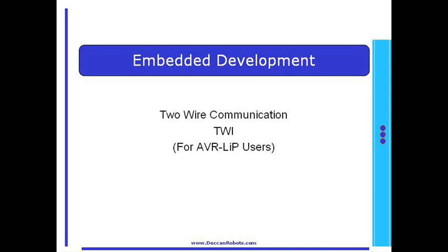The 8255 IC was used to convert one 8-bit port to multiple 8-bit ports. These multiple expanded ports were used to connect with other parallel interface devices like ADC, keypad etc. In this type of design, at least 12 pins of the microcontroller were used.